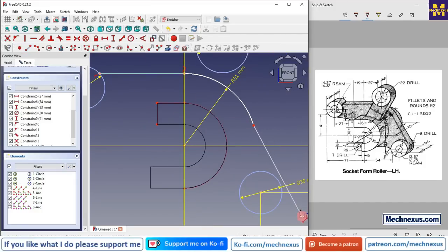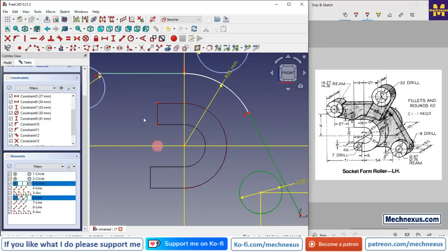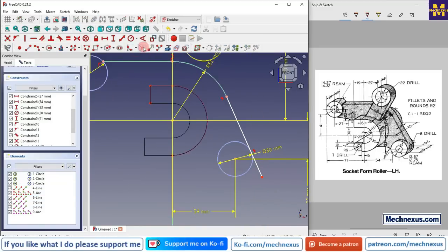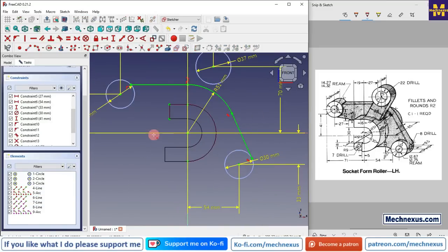And here we will create a line which will be tangent. So we will select a line tool and select these and this and add a tangent, also select this and this and add a tangent, and now I will use the trim tool to trim it.